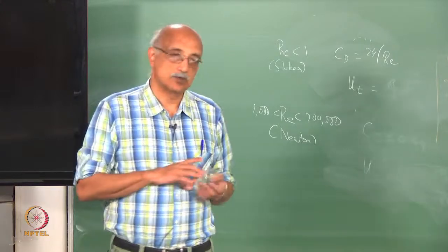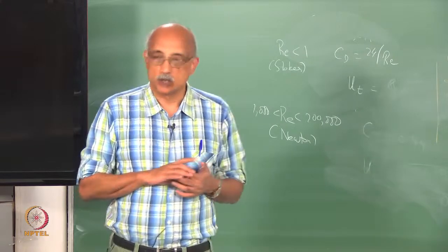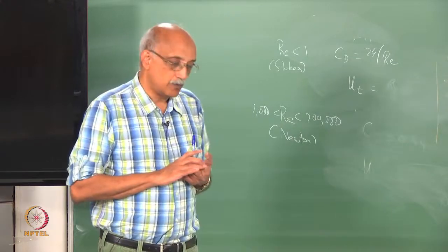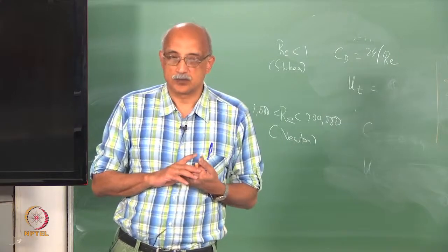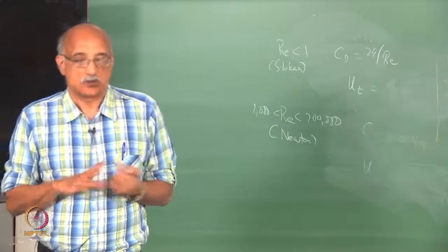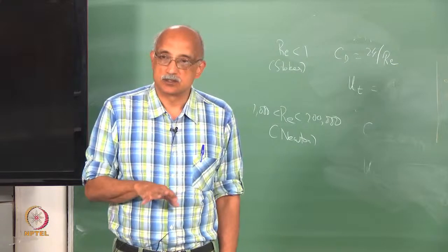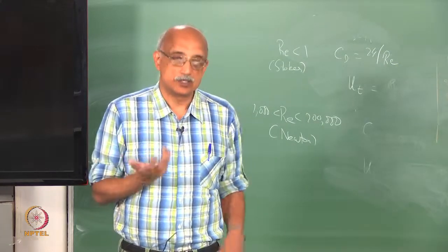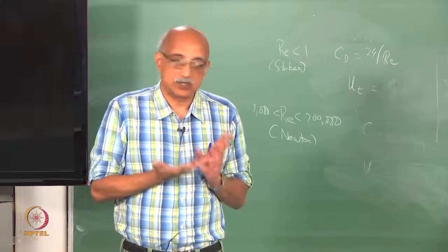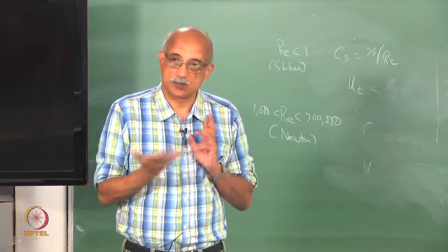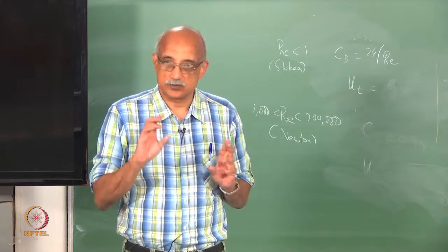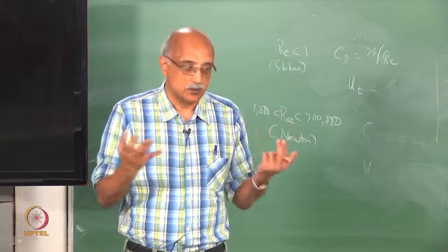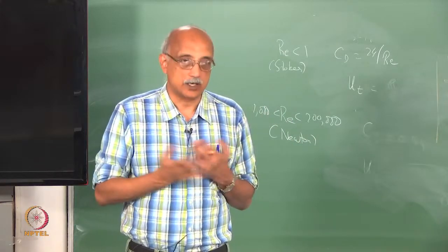Shape actually has greater influence when the particle size is larger, and the reason for that, of course, is that very fine particles, if you go down to the nano sizes, behave like vapor molecules in general. So that ability to interact with each other and accommodate each other is much greater, and it's virtually independent of shape. But as particle size increases, shape also becomes an important characteristic.